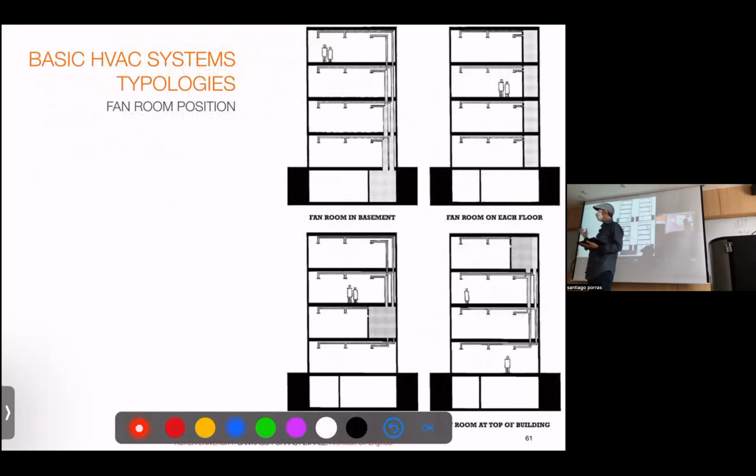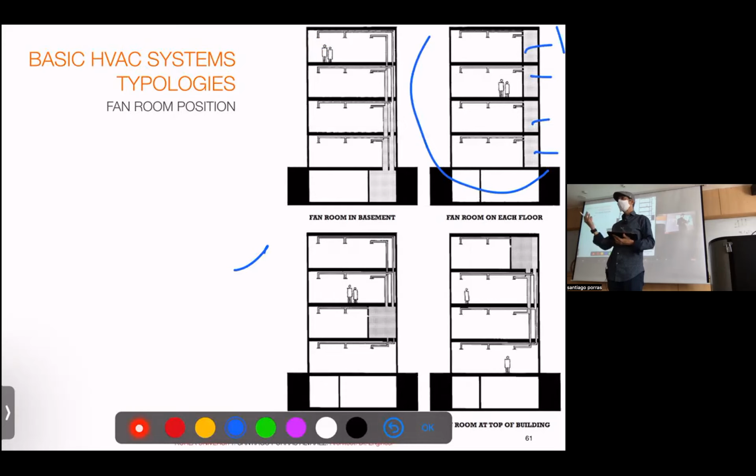And then once we choose the system, we have to decide where to put the air handling units and the machines, right? And there's like 4 options we have. Of course, this is very simple, but when you have your buildings, you have to really decide how to put it, especially those having a high-rise or very long buildings. You may need to divide in bits, right? So this kind of a floor-by-floor division is great for very much decentralized buildings, so you have a smaller space used there, right? In smaller buildings, you may have also that air handling unit anywhere.